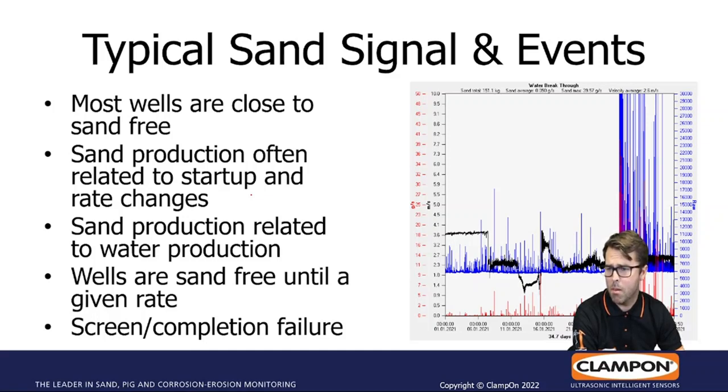But we also have wells which have a more changeable gas liquid ratio, external noise from other sources, etc., which makes things more difficult. Also, high viscosity can be an issue. We can see that sand production very often is related to startup and water production. We can also see that many wells are sand-free until a given rate.